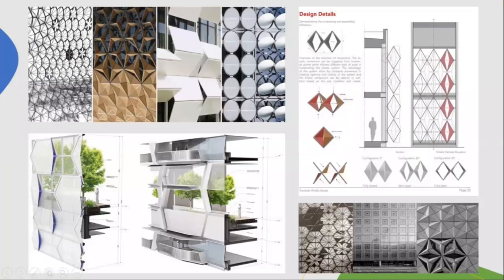So this is a basic example of what kinetic facades do and their important function in our particular workflow. We optimized our particular model from the start, from the conceptual design itself, using Insight 360 and Formit 360. And after the conceptual design, we developed the model further or detailed the model further using Revit and optimized the model again using Insight 360.